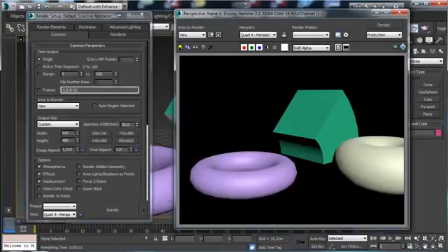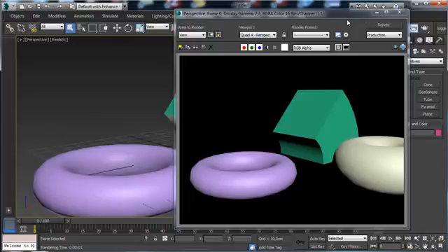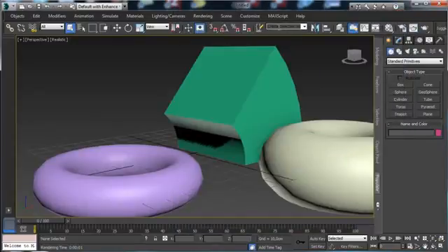But in case you are using, for example, a bitmap with no standard gamma, you have to set the gamma manually. It is important when you, for example, need to work with bump maps or normal maps, where you need to work with a pixel in a more complex way. But in this way there are fewer problems understanding how to manage everything for the basic users, because everything is done by 3ds Max by default.